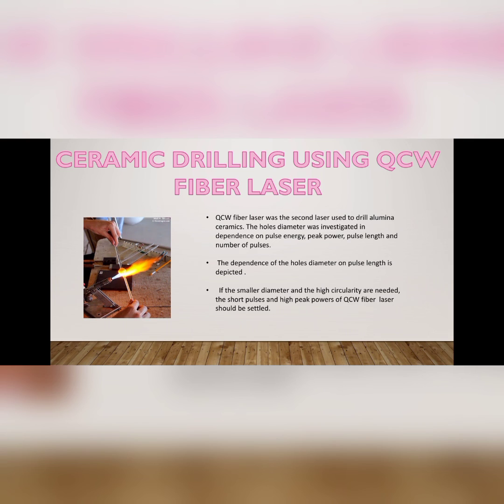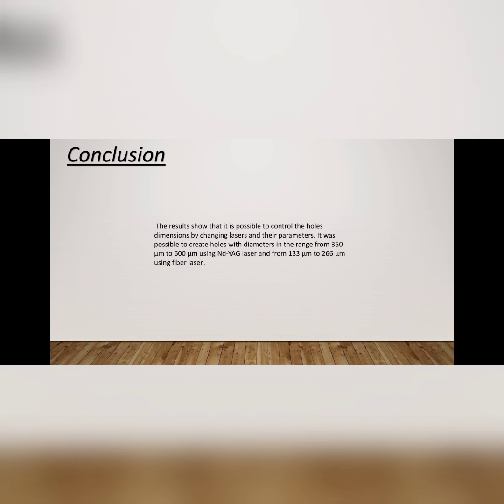Coming to the part of ceramic drilling using a QCW fiber laser. QCW fiber lasers were used for drilling aluminium ceramic. The hole diameters are investigated in dependence on pulse energy, peak power, pulse length and number of pulses. The dependence of the hole diameters on the wavelength is discussed.